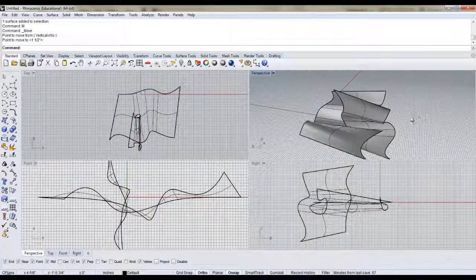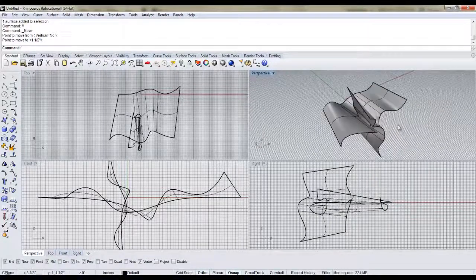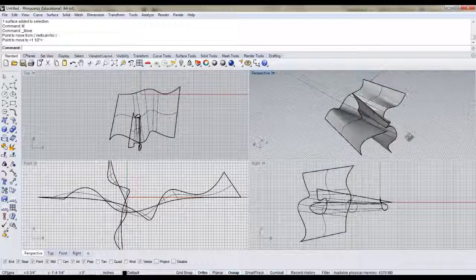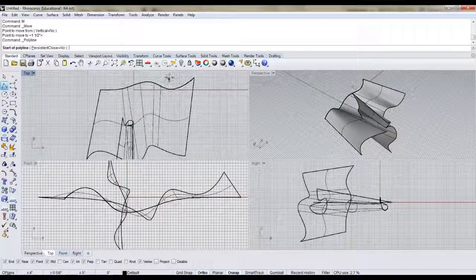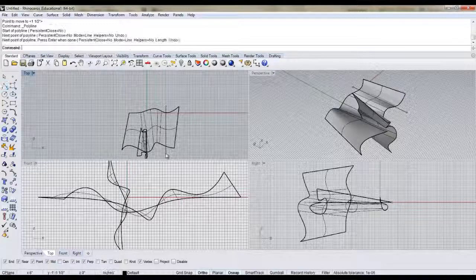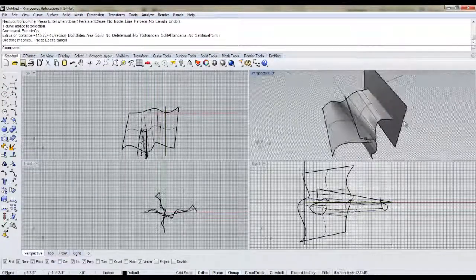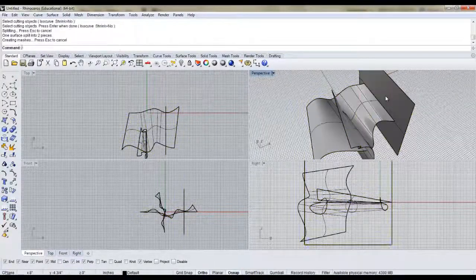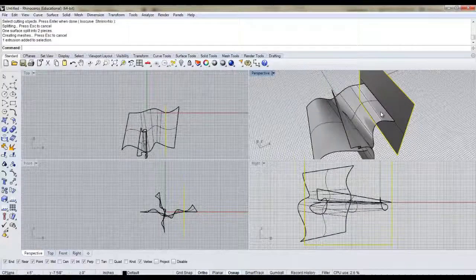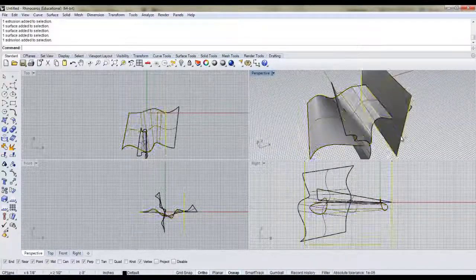Okay. So then in terms of these two surfaces, some of you are having issues with intersections when you Make2D. Ideally, if there is an intersection that goes completely across an object, as I'll show you here, if you type in the term split, it'll split the object that it's completely intersecting, and then you'll get that intersection between the two of them. But you'll also get two separate surfaces from the one that you split.